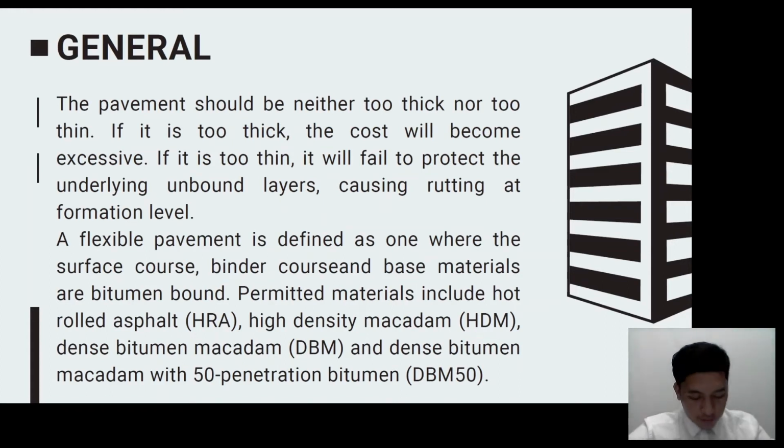First off, we have flexible pavement. Pavements are called either flexible or rigid according to their relative flexural stiffness. Flexible pavements have base courses of broken stone pieces either compacted into place in the style of macadam or glued together with bitumen to form the asphalt.